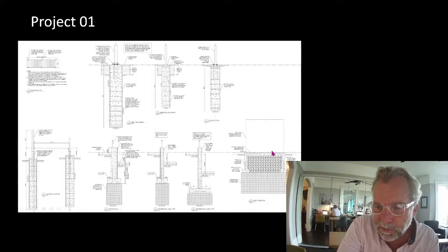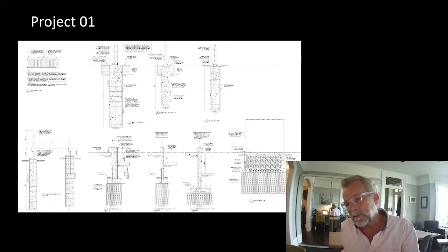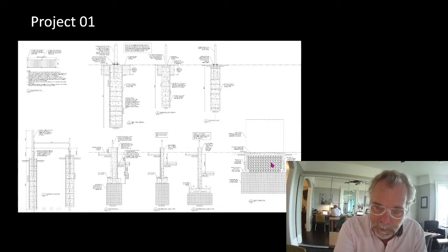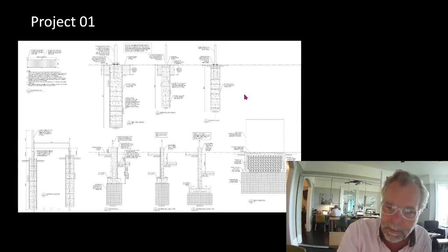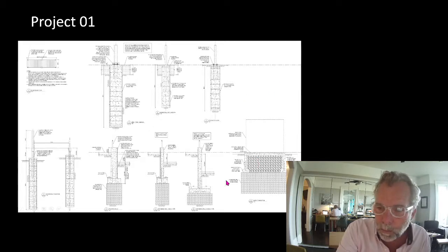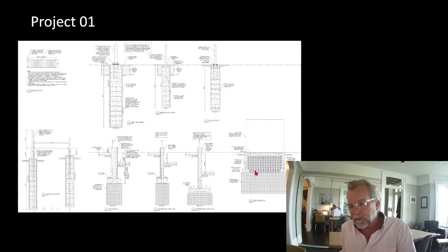This is another strategy for a frost slab. This is actually probably a transformer or something. See what we've done here is it's filled completely with clear crushed stone, and we don't have an airspace. So you may say, well, if we don't have an airspace, isn't it vulnerable to heave, since frost can go directly through there? And that is true. Except that, for one thing, how does water get in there? Water can't get in from above, and waterborne water can't wick up into this zone because it's clear crushed stone.